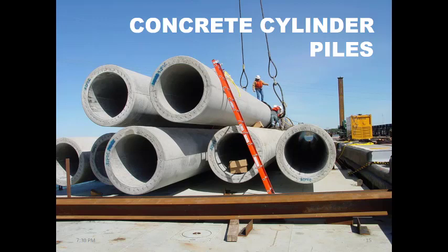You should be really careful about where you load while the pile is still in rest position, so it's not under its working position, because piles are designed to support the load that is coming vertically, not from the side perpendicular to its axis. So if you load it improperly, there is a chance that you may crack the wall of the pile under its own weight, which is something that no one wants to have in a project, because the integrity of the structure will be affected.